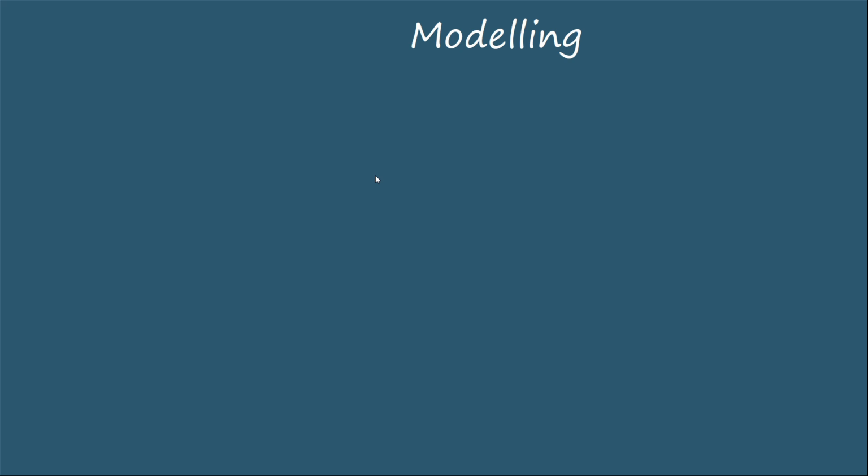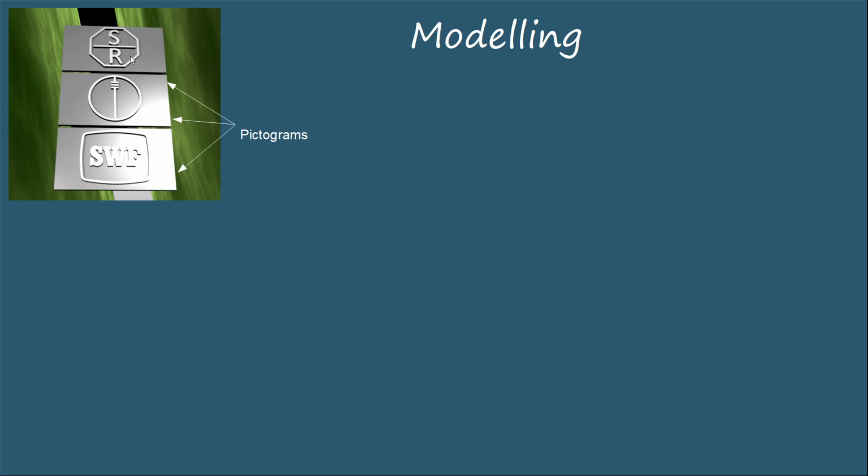What is special about the modeling of the objects for this animation? The pictograms of the broadcasting companies are created with multiple approaches. In some cases, I used Bezier curves to create certain types of fonts, like this one here. I also used a different approach for some of the pictograms, like this monitoring symbol here, where I used a mesh object in combination with subdivision surface modifier. And then for some other fonts, I used the predefined system fonts, which are available in the Windows operating system.